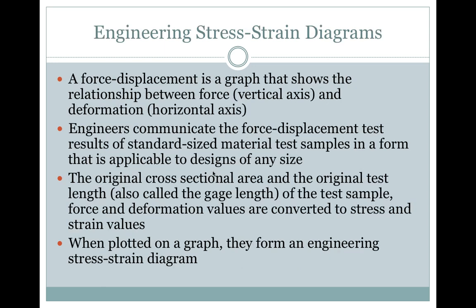Engineering stress-strain diagrams. A force displacement curve is a graph that shows the relationship between force and deformation. Engineers communicate the force displacement test results of standard size material test samples in a form that is applicable to design of any size. Using the original cross-sectional area and the original test length, also called the gauge length, of the test sample, force and deformation values are converted to stress and strain values. When plotted on a graph, they form an engineering stress-strain diagram.